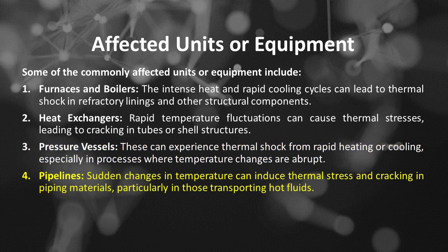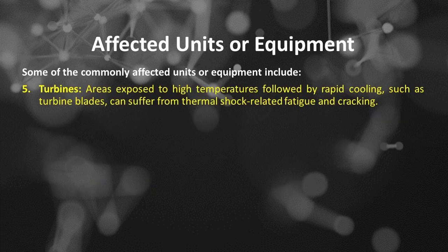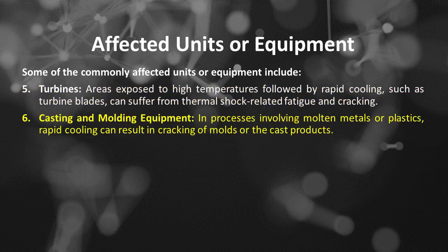Number 4 is pipelines. Sudden changes in temperature can induce thermal stress and cracking in piping materials, particularly in those transporting hot fluids. Number 5 is turbines. Areas exposed to high temperatures followed by rapid cooling, such as turbine blades, can suffer from thermal shock-related fatigue and cracking.